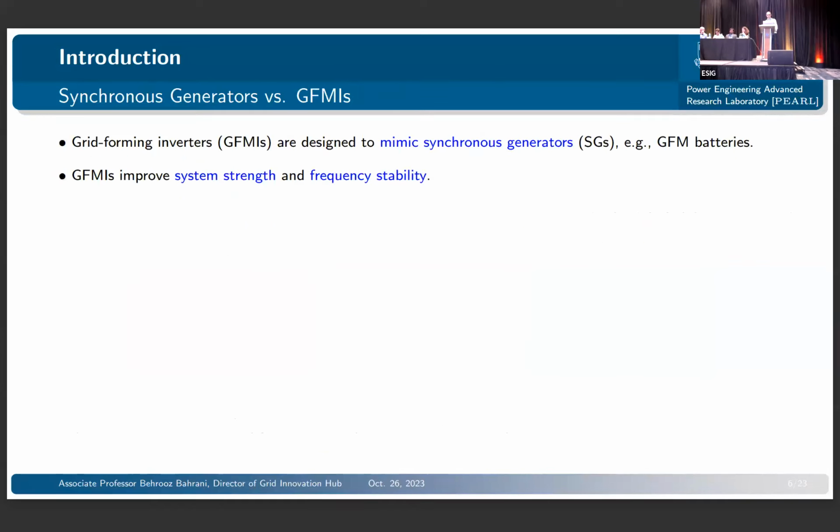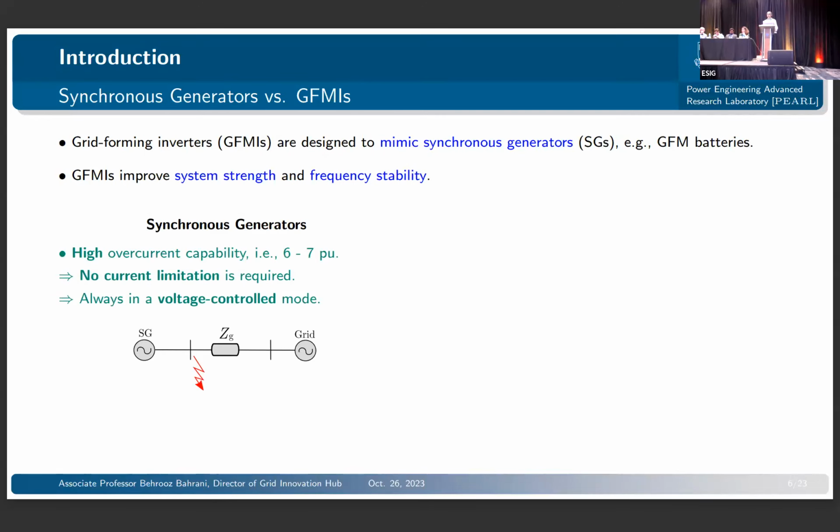This is what we've been doing, and we've been trying to look into transient stability of grid forming inverters particularly. But again, before going there, a quick recap of a comparison between synchronous generators and grid forming inverters. Obviously, there are a number of different ways of implementing grid forming inverters, but the more accepted one, which is a virtual synchronous generator, tries to mimic the performance of a synchronous generator. Typically, they can improve your system strength and frequency stability.